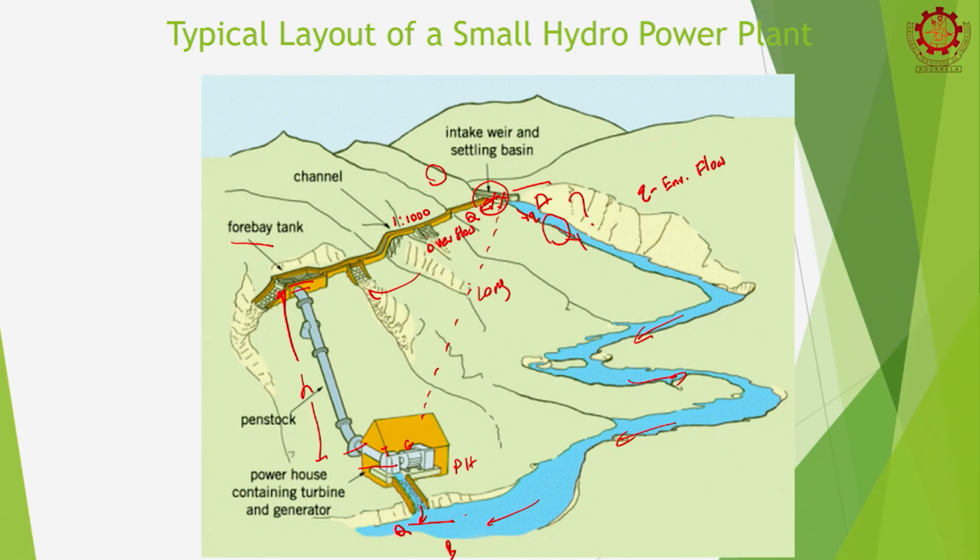In the flood season the water level will rise due to floods. So, your power plant should not be inundated, otherwise your control equipment and generator will go under water. In technical terms, we say it should be above the 100-year flood level. How to identify those things we will discuss in the coming topics.